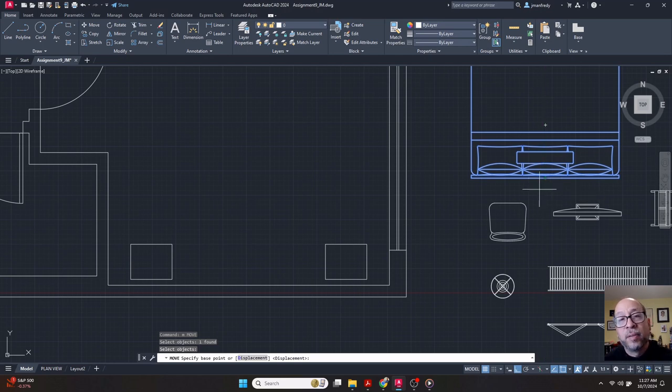If it cannot find the midpoint, then simply go into the O snaps here and choose the midpoint snap, or you can type the snaps in the middle of a command. Let's say you didn't include midpoint. You can actually type the first 3 letters of the O snap and it activates that O snap immediately and ignores all the other ones that are available while you're in the middle of a command. If I type MID, enter, it'll look for midpoints. But currently, my midpoint is active, so I can see it here.